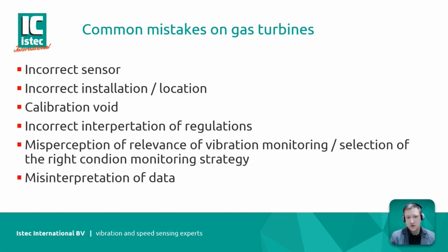Installation: the location, where do I measure? How is the path, the transfer of vibrations towards my sensor? You want to have it as direct as possible, so you want to measure as close as possible to the source of your vibration. And you also want to install your sensor properly. Again, if it's in a hot environment, can I route my cable properly? Is the surface where I mount my sensor perpendicular to my sensor, so I don't put any strain on the casing of the sensor?